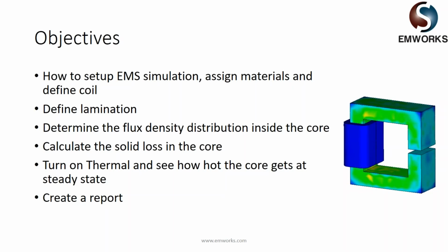You can then solve using an automatic mesh generation process inside the program, and then you can take a look at 3D results in the form of magnetic flux density, the field intensity, etc., both as 3D plots and vector plots. You can also compute the solid losses, and finally you can study the temperature distribution in the core by coupling it to a steady state thermal simulation. Okay. And finally, one can create simulation reports with the click of a button. It's done automatically for you.